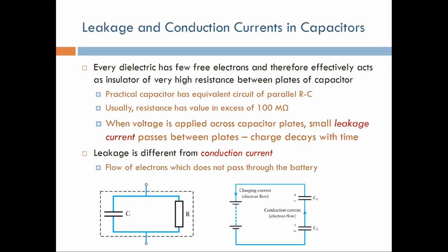No. Even if you turn it off completely, and you leave it for a few days, you're going to come back and find it at like 50%. This is because you have a leakage current. Leakage means that the current leaks between the two plates of the capacitor through the very high resistance of the dielectric. It's a very small current.